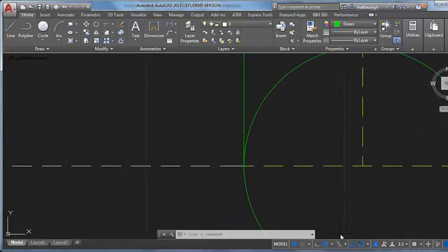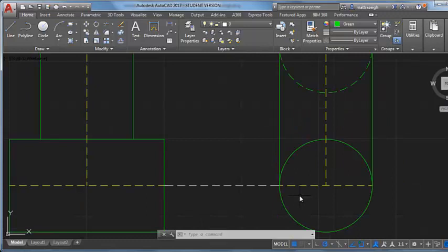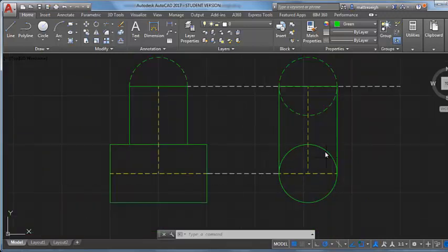So back to my other drawing here. This one in particular, I think I drew it up as 14 gauge. So I would probably almost V that all the way down. 14 gauge is just barely over a 1/16 of an inch thick, so you don't have that going on. So it's something that I maybe would take all the way down like this, like I'm going to draw this. All right, so that's our branch coming down. Back to my drawing here. I'm going to trim this out.